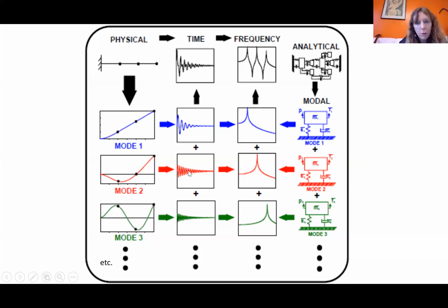so you can see the periods are smaller. And then the third mode. So this is in the time domain. Basically the time response is a linear combination of these responses. And you can see it as well in the frequency domain. The two are linked by FFT, fast Fourier transform. And you can see the modes here. You see the 3 peaks corresponding to the 3 modes, and you can decompose them as 3 individual peaks that you sum.